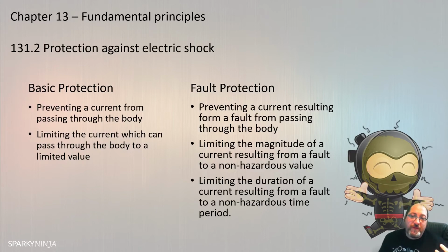So from our everyday principle, we're looking at barriers, enclosures, obstacles, placing out of reach. What stops you touching things that are live? So that's the basic. But we also need to think about what could happen in a fault scenario. So we have fault protection to go with that.